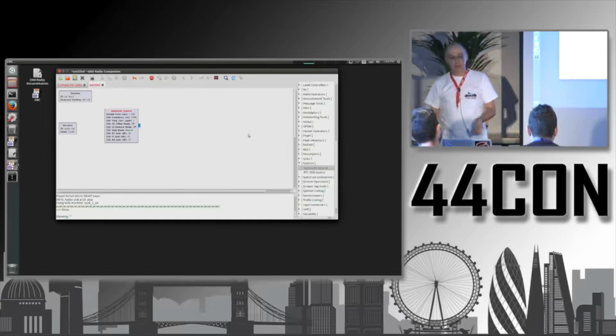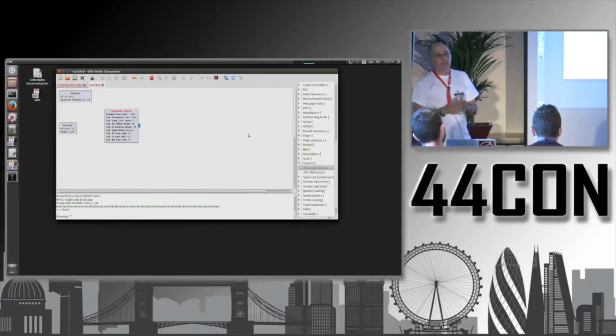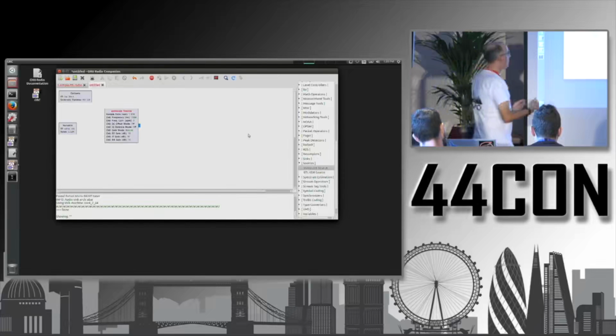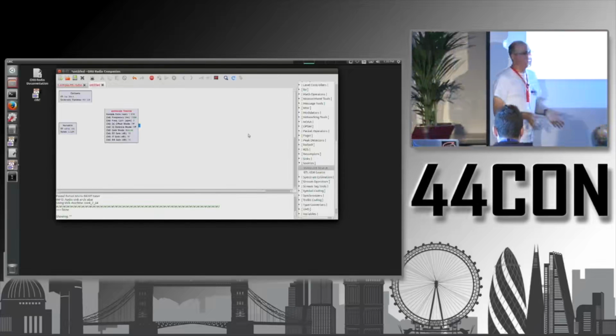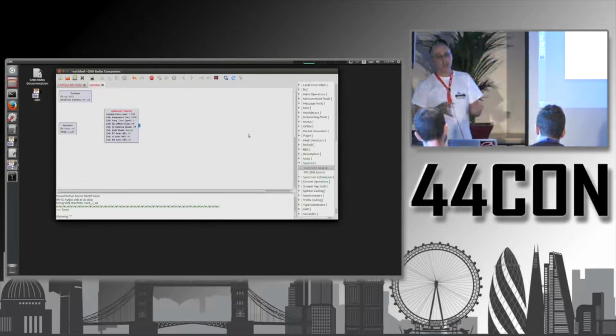FM, frequency modulation, it's another method, but there instead of the amplitude, it's a frequency of the carrier that is modulated. Okay? So, for example, we are transmitting at 100 megahertz. Well, we will make some changes to it according to the audio signal.